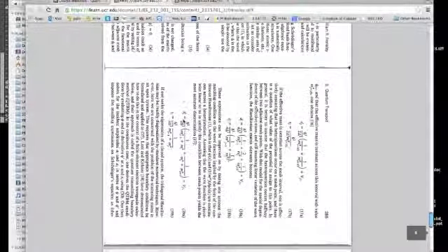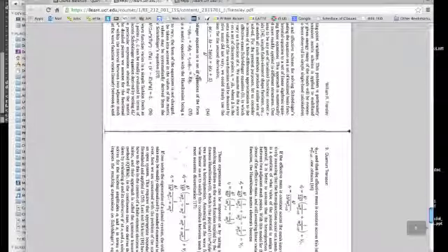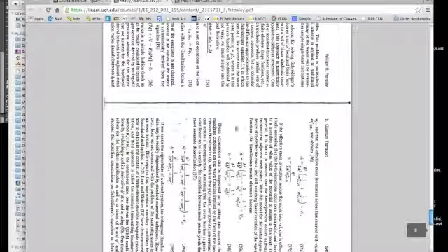Finally working down, I think what I do is I go to this single band tight binding model that we became so familiar with in EE208. What Bill does is he starts off with the effective mass equation and then discretizes it using finite differences. But we showed in 208 that when you do this, it's exactly formally identical to nearest neighbor tight binding. So the form of the discretized Hamiltonian he gets is exactly what we get from our nearest neighbor tight binding model.